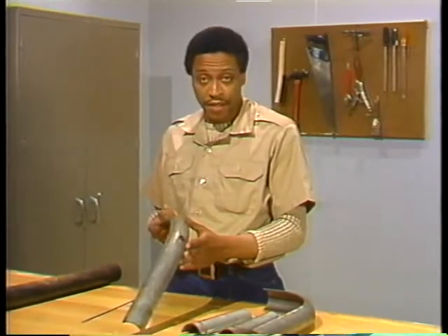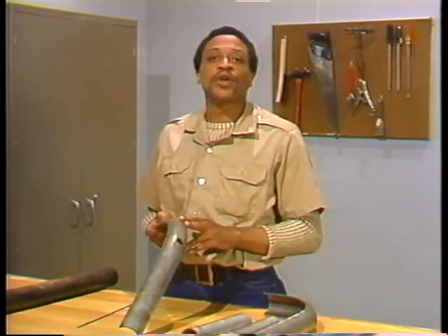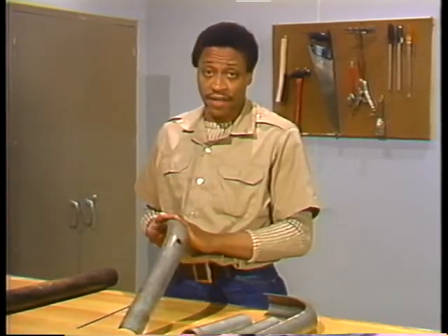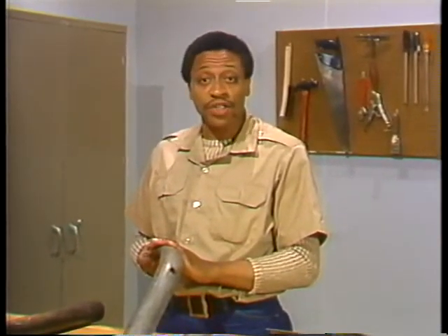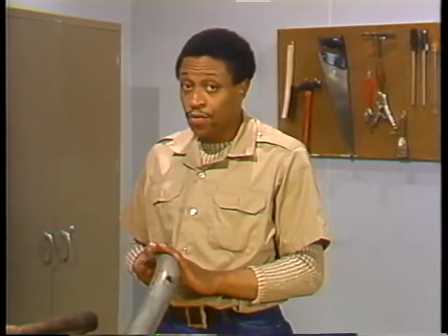A tube shield is easy to install and requires little, if any, welding. However, it's not effective against thinning caused by corrosion, and it does not reinforce the tube like cladding does. Let's stop here for a few minutes so you can make sure that all the information is clear to you.